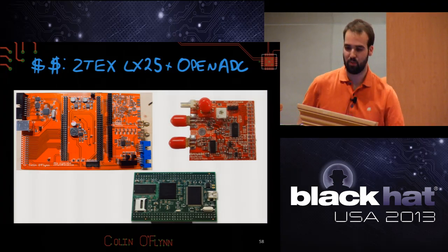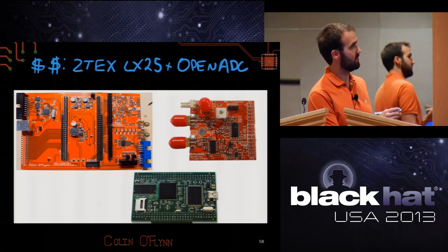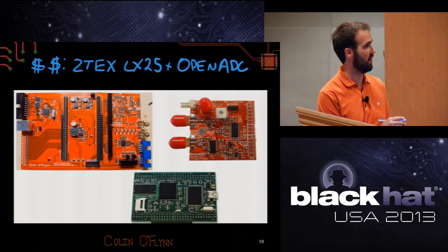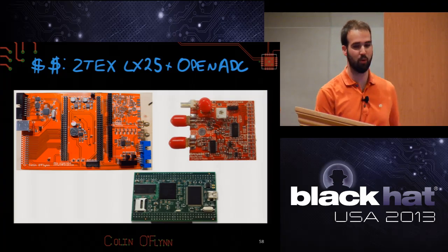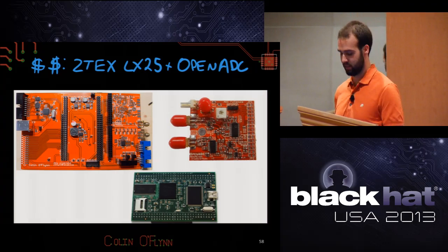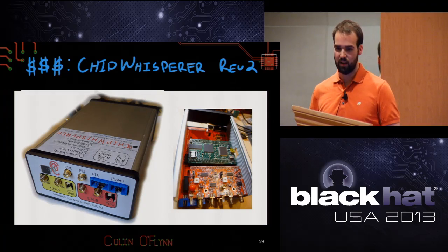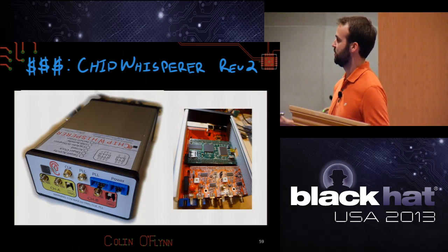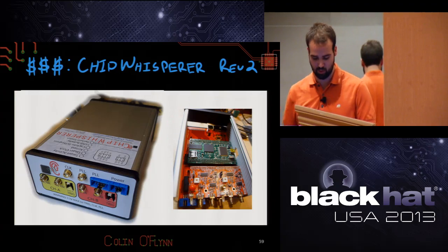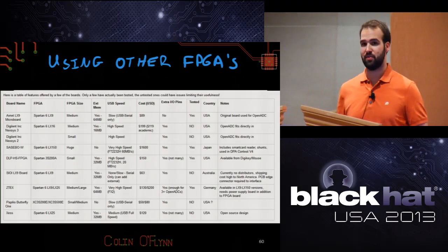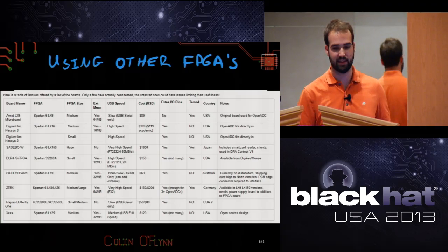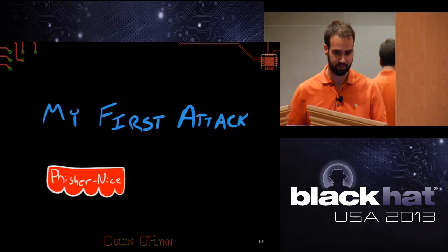Instead, this is the latest hardware I've designed that I'll show you here. So there's these boards, all the designs are here. And you can use this with an FPGA and either mount this ADC board or build an ADC board on it. When you combine everything, you get a complete system for doing this side channel analysis. And eventually I'm trying to build and sell them as a complete package, but this is the exact same thing as this. It's just one's pre-built, one requires you to do a bunch of soldering. Or you can use, if you do FPGA development already, you may have a suitable board. Typically any Spartan 6 board, because that's what I'm using, can easily be modified.